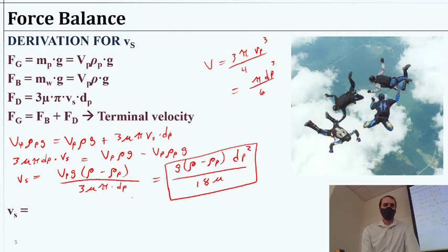So that's our final solution, and this is what we'll use when doing sedimentation in this class, with regards to finding the settling velocity if we have some information about the particle dimensions. We can use this for quite a few things, and as you see, we've got a couple of temperature dependent parameters in here, the rho for the water and the dynamic viscosity. We could maybe do this on the moon, but the force of gravity is not very good on the moon, so this probably would not be a very effective treatment option if you had to treat water on the moon, for example.